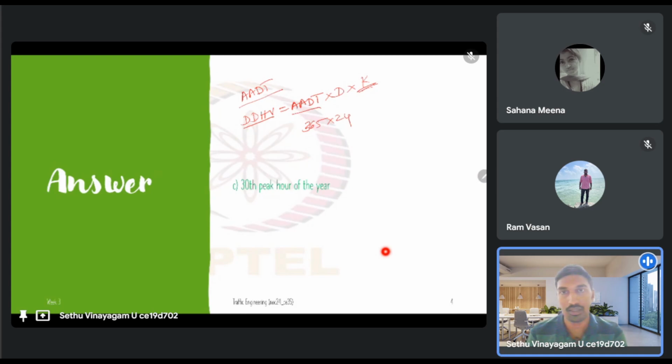So we measure for 24 hours for all the hours in all the days of the year, and then take the average of all this, right? So that's AADT. Which means we have 365 into 24 hourly demand observations. Now what we will do is put it in descending order, right? So we have these many observations, we put them in descending order, something like this. They have the demand, and this is a different number of observations sorted in descending order.